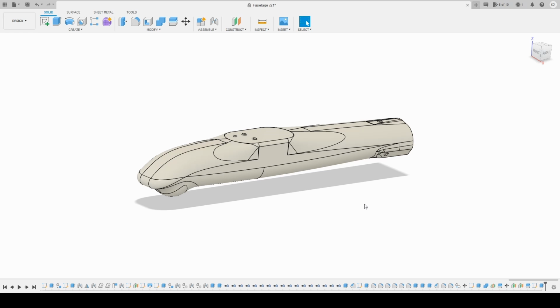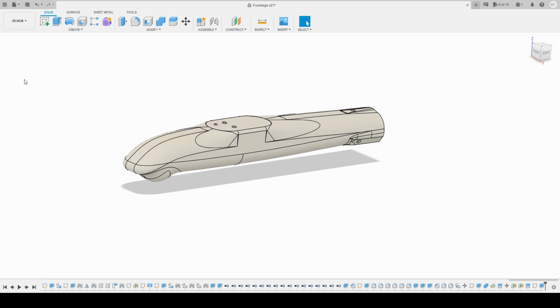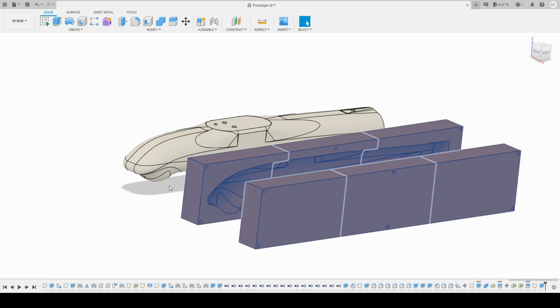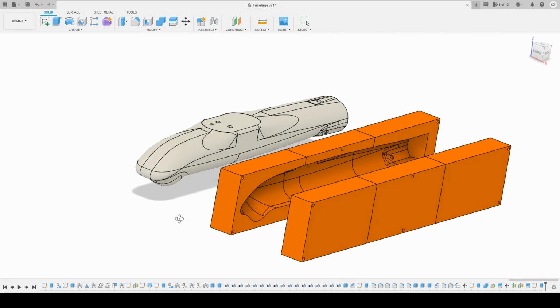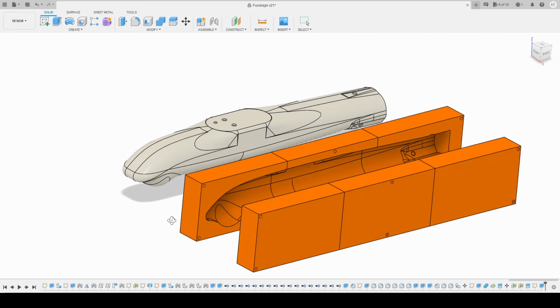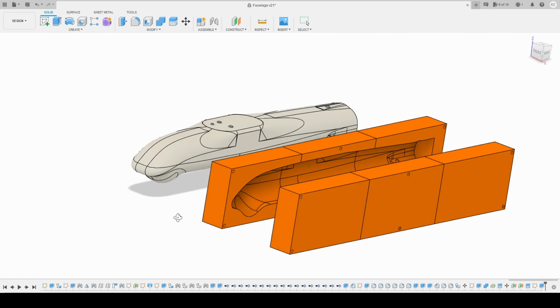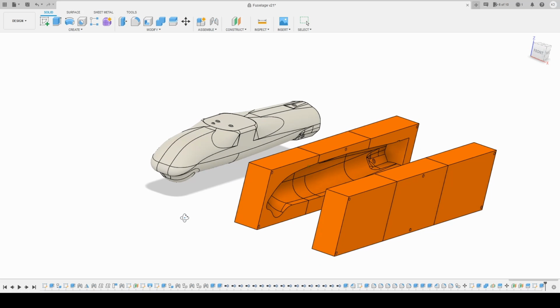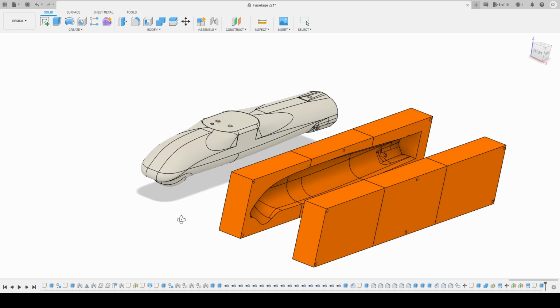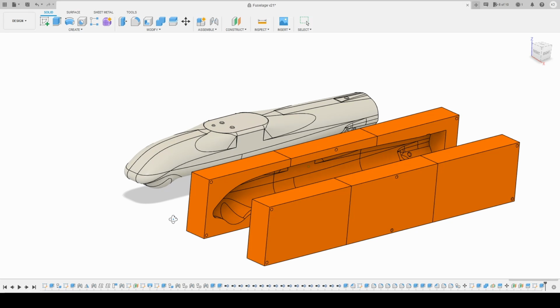You might 3D print it, where you put the STL through a slicer and generate the G code for a machine to use. Or you might go ahead and make a mold so that you can make a composite piece out of it like this, but that comes along with its own challenges. The geometry might be too complex to do without vacuum bagging or some other form fitting technique to get the contours into the composites. So what else can you do?